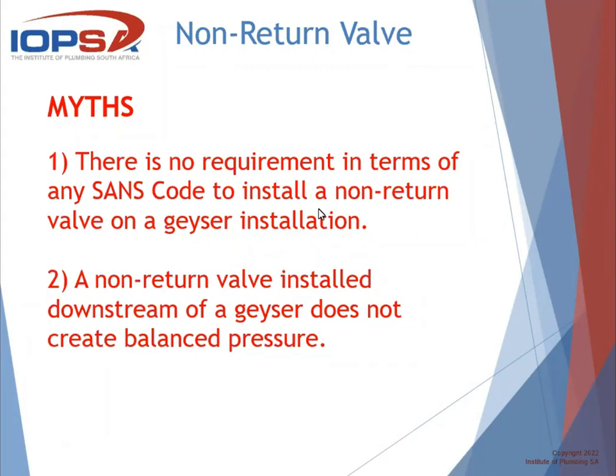And when they talk about backflow prevention function, it means we're talking about safety protocols now, preventing contamination of potable water. So the performance requirements jump from kind of wishy-washy to very specific. So a backflow prevention device is something very specific. It is there to prevent backflow, which is there to prevent contamination of potable water, which means it becomes quite important. It has to perform to better standards than just a single check valve can. So I just wanted to put that out there just for clarification.